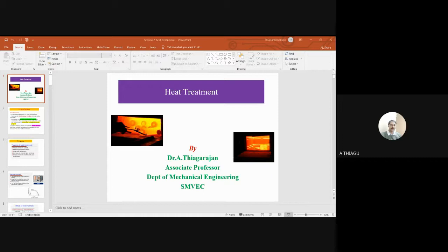Okay, so these kinds of internal stresses we are positioned to remove by means of the stress relief annealing process. Here what will be modified is from plastic deformation processes such as machining, grinding, non-uniform cooling of metal that was processed at a fabricated elevated temperature, and phase transformation that is induced upon cooling when the parent and product phases have different densities.